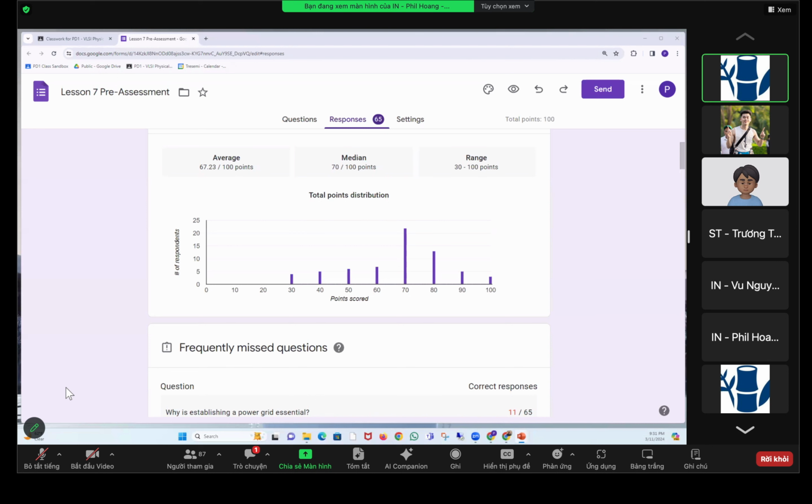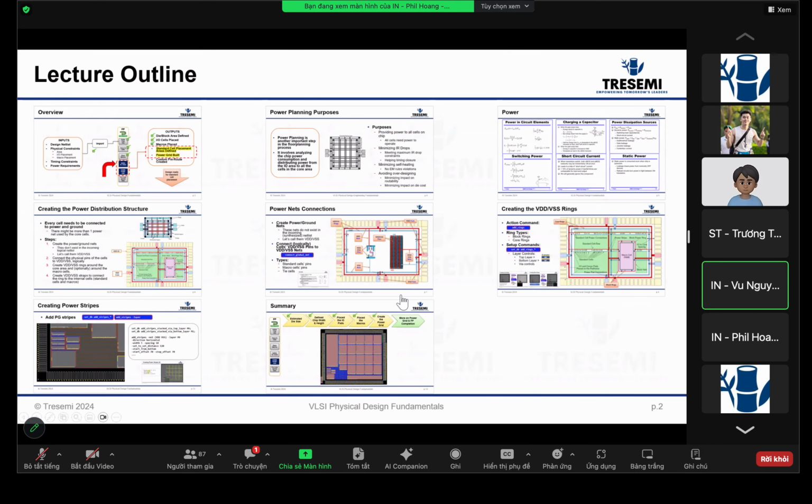No, then it took up some space, right? Yes. Okay. So it's a must. If you don't have it, your chip will not be reliable. I mean, the tie cells are very important. Starting at about 130 nanometer design and below, you know, at a bigger geometry it's not a must, but at 130 and below, you gotta have it.